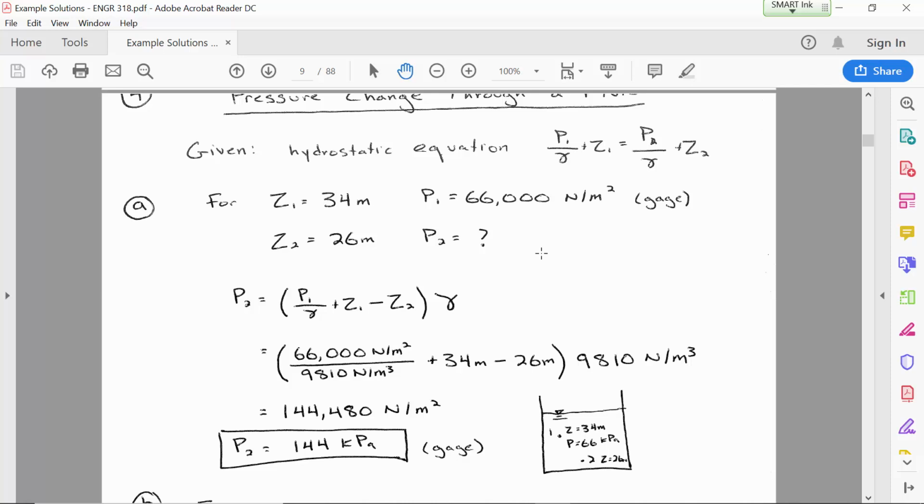Either one's okay. Now, as I've written on the board, the way that you can convert between gauge pressure and absolute is if you're given the gauge pressure and you want to know the absolute pressure, you have to add on the atmospheric pressure that was ignored the first time around when you had the gauge measurement. So P absolute is P gauge plus the atmospheric pressure.